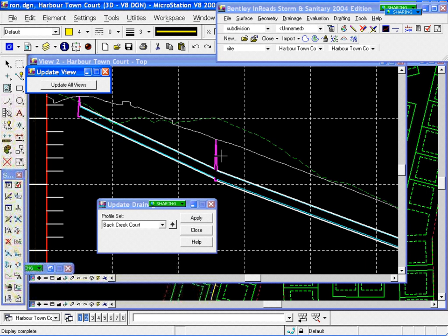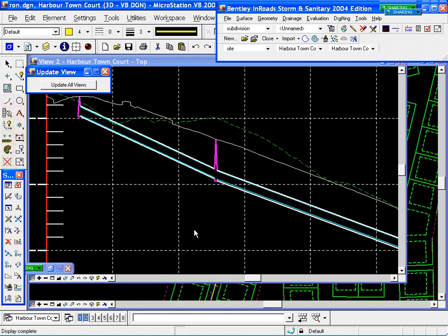Okay? And so that easily, if I have a modification to my DTM, I can move my entire network relative to the design change that I had. It can also correct it if you do like I did and use the wrong DTM. In this case, I used the pre-construction DTM. Maybe perhaps you used a preliminary DTM and came back and had a final DTM, and you need to raise everything to that. So it's very easy to correct and move the items that you've got within that.